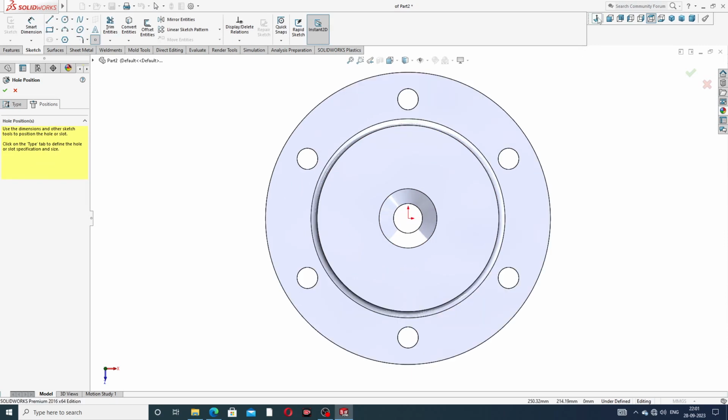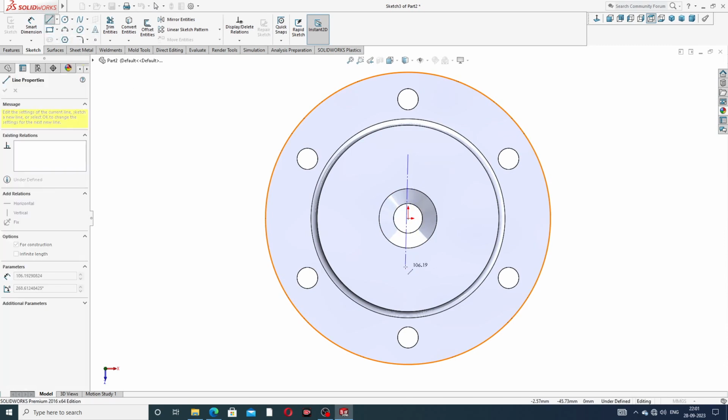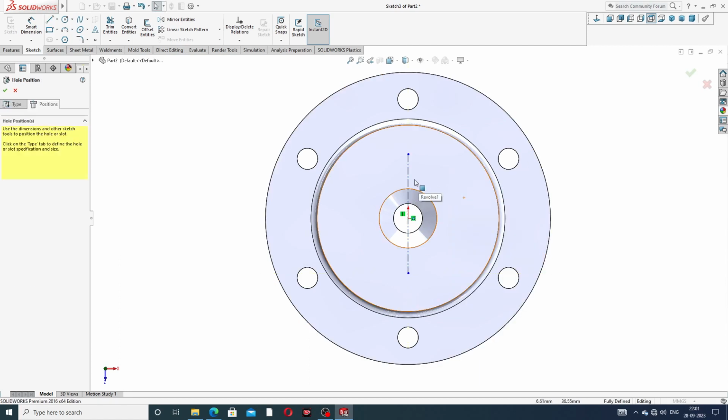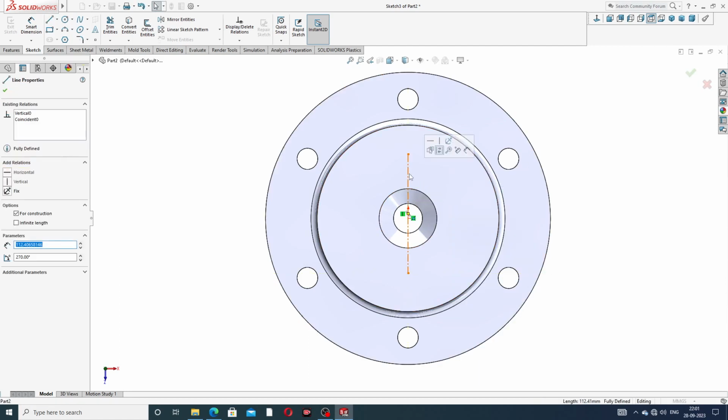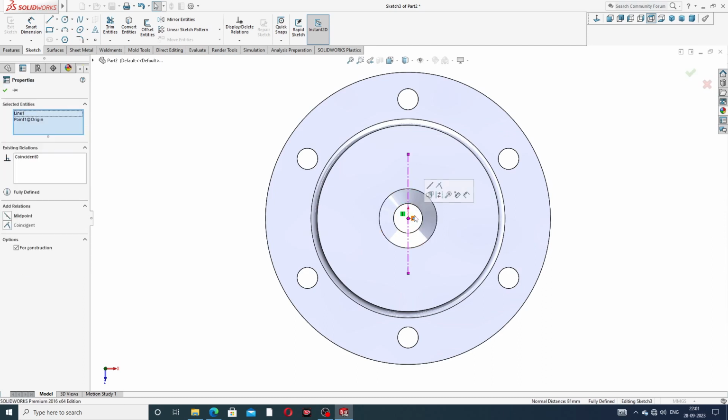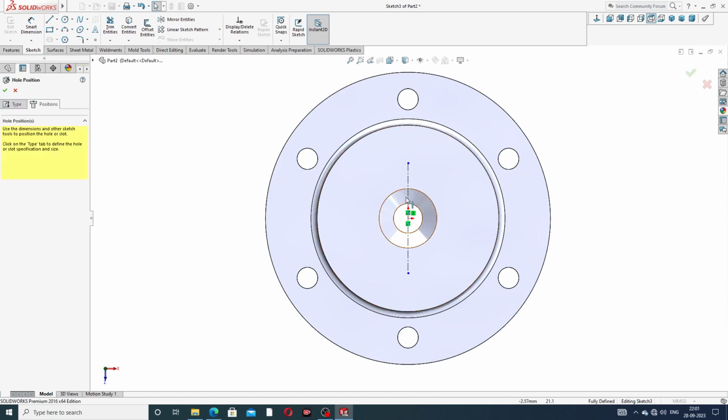And this is Sketch Normal. Okay, and draw a reference line. The reference line is perfect, drawn here, because this uses a mid plane. Okay, select this line and press the Ctrl button and select this point and use Midpoint. Okay, and all is perfect, and the dimension is mentioned here.